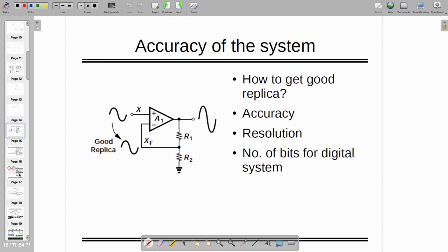So here the most important part is I want to replicate the signal at the plus terminal to the minus. I'm applying something here at plus. When I get it fed back, if you remember the negative feedback block diagram, it gets a replica here, so that the difference of these two is exactly identical, and we are getting zero output at the input of the feed forward system.